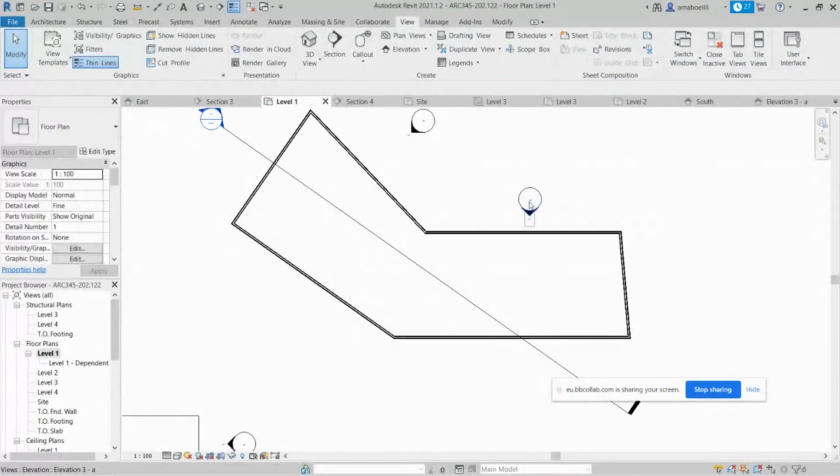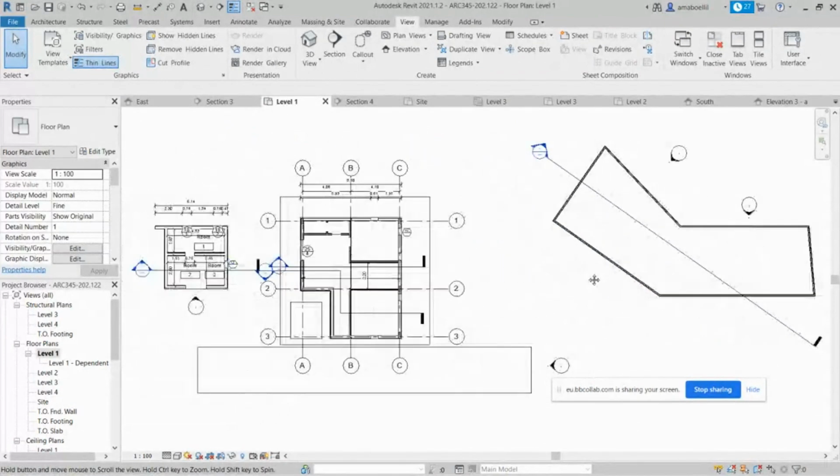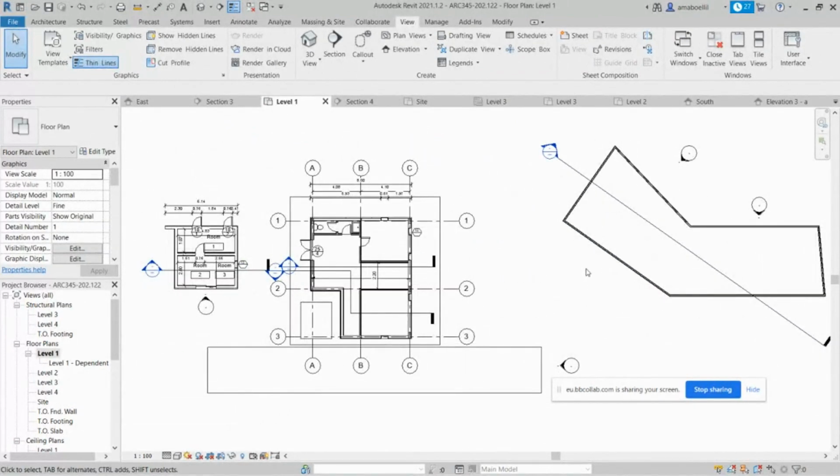And of course, once you locate the elevation, it will automatically write up the elevation number here, and it will show the information about where it's located in which drawing. And pay attention, since we shifted to the section and elevation, we started to use A2, not A1 anymore. A1 is for plans, A2 for sections and elevations, and make sure that you adjust the numbers based on this.